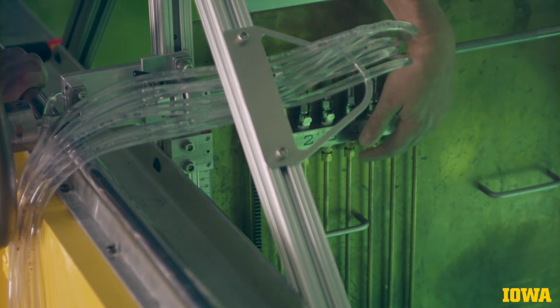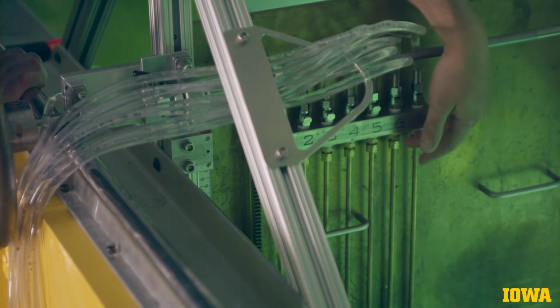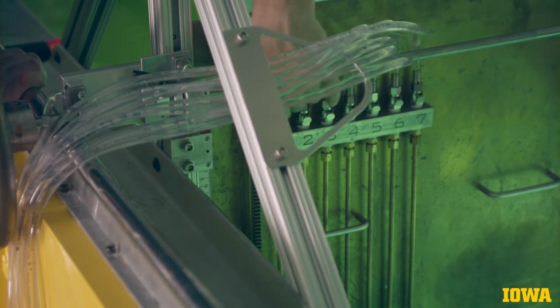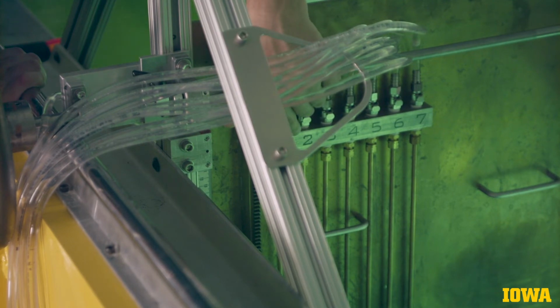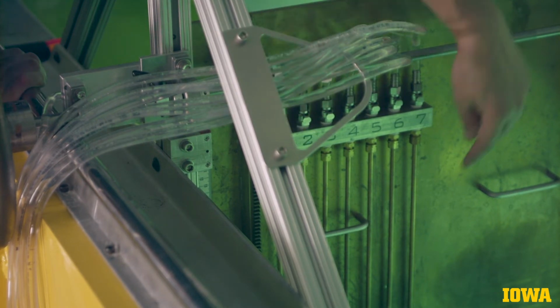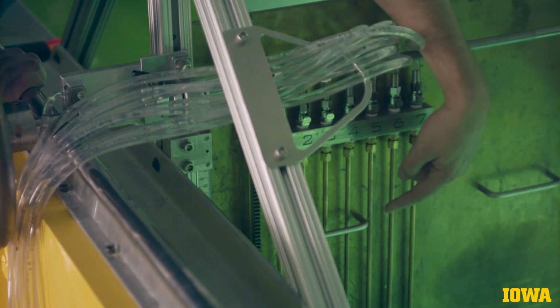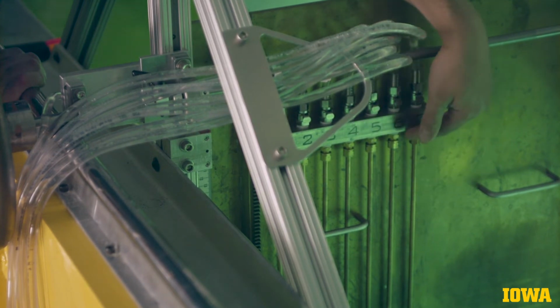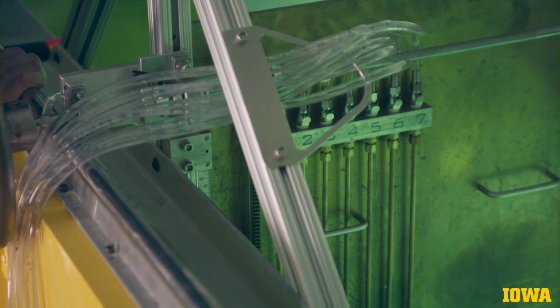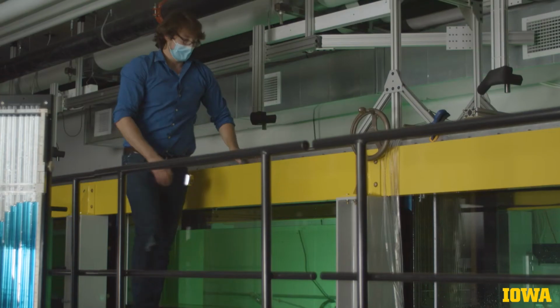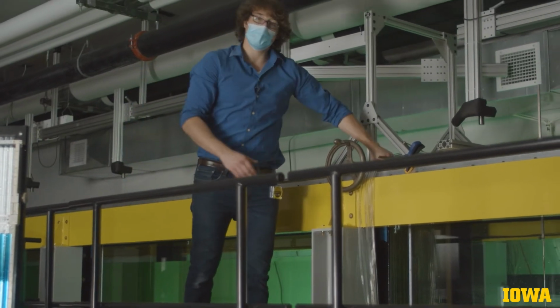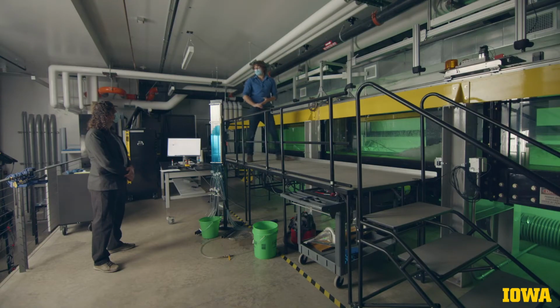Closer to the center of the flow channel, you can see a total of 7 brass tubes, which are numbered 1 through 7. These correspond to the pressure taps at different heights, which you can see by the 90-degree kinks in each of the brass tubes, and which correspond also to the bank of 7 piezometers discussed earlier. This one upstream tube and the 7 pressure taps are then connected to this bank of manometers, or piezometers.